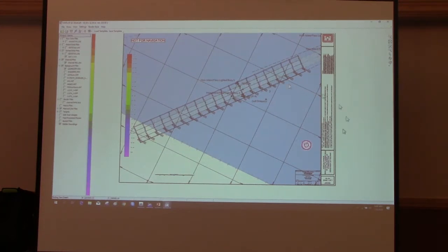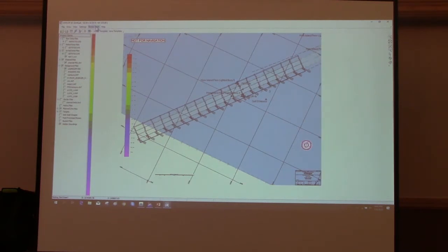Now, a lot of the settings, there's different style borders available in HYPACK, and if you click on the border drop-down menu, if I choose none, you'll see it won't draw anything. A single border just draws a single line around the edge of the plotting sheet. Double border, I believe, creates a little 2 centimeter space around with the second border. Double border with the title area creates a title area off to the right of your plotting sheet.